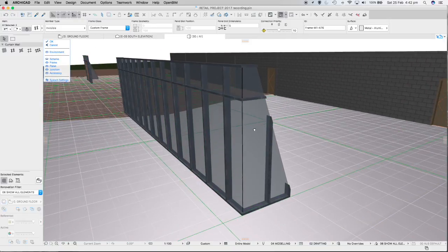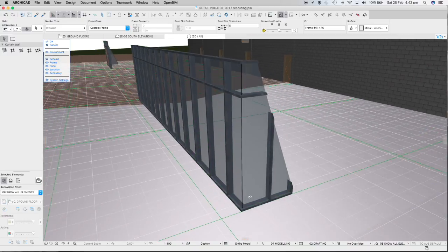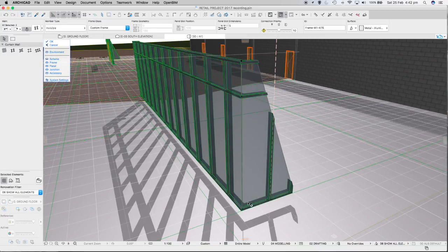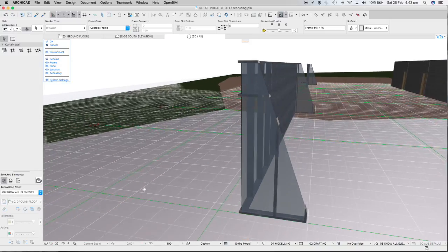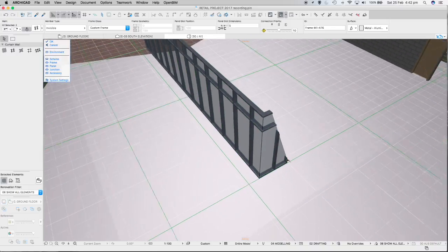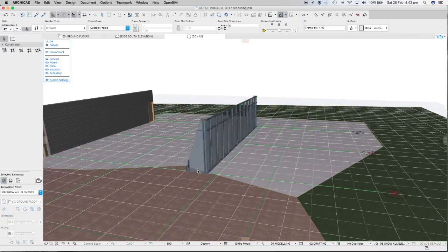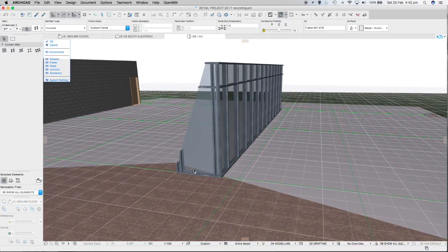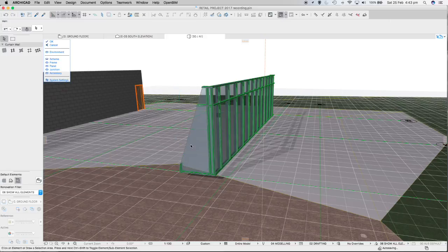And you can see now we've made this corner element here trim very nicely into the corner, very easily, without a lot of mucking around. The only thing that we're missing is this framing element through the side. We'll talk about that in a second, but we might as well just tidy up this other end in a similar way. So I think it was this one that we got rid of. So I'm going to click this white icon to make sure I get everything going through, and delete.